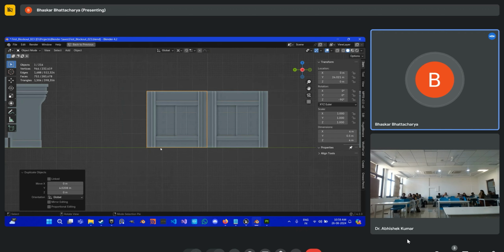So whenever we make tile-level assets, we will ensure that this is fixed on a grid, so that we will have no problems when we are tiling this. Ideally, it is preferred to be in powers of two, but you are not forced to do that. For my assets in this one, I believe these are 3 meter by 3 meter because I tested and 4 meter was too high. So this is 3 meter by 3 meter, all the assets.